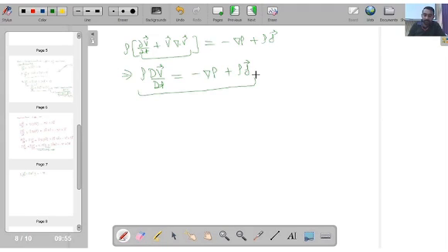For an inviscid flow situation, the forces acting on the body are pressure and the body force. So the right hand side is pressure and the body force, and the left hand side has to be mass into acceleration, which we write as rho into dv vector by dt, where v is velocity. If I have a moving fluid element whose velocity is given by v vector, then rho dv vector by dt will be its total acceleration. So mass into acceleration is equal to the net external forces acting on the body. This particular form is nothing but the non-conservative form of the momentum equation.